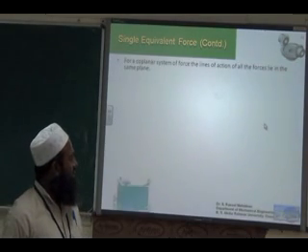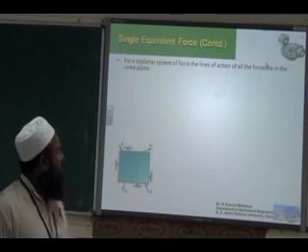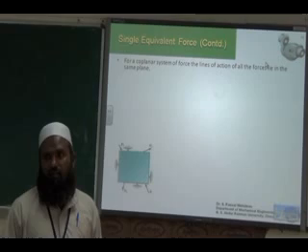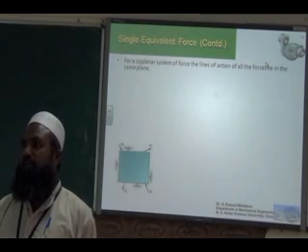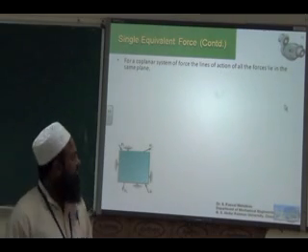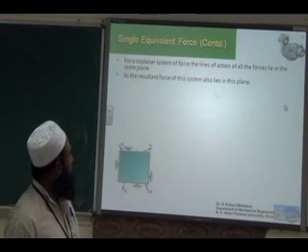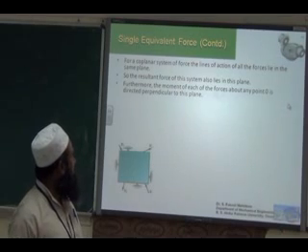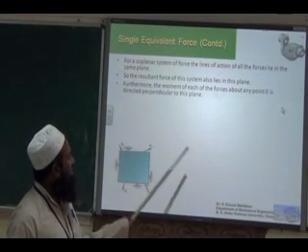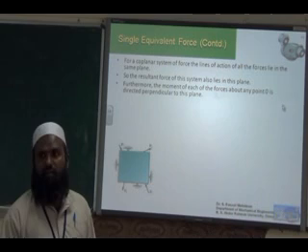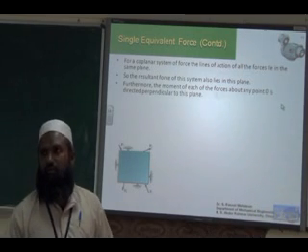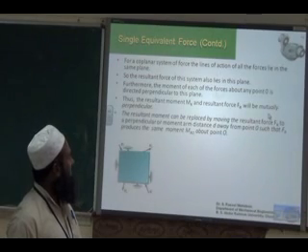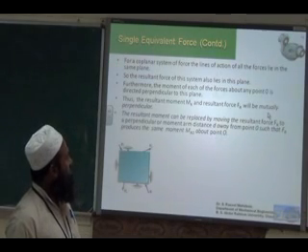Suppose they are not concurrent: you have forces acting at different points, but they are coplanar, acting in the same plane. So the resultant should also lie on the same plane. We have to transmit all the forces to a single point of our interest, say point O. When you transmit, it produces a moment. The resultant moment and resultant force.